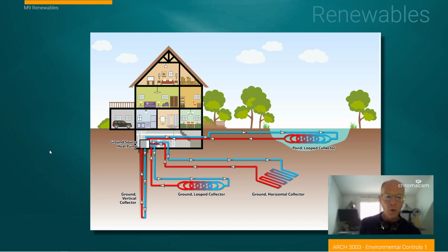So at first, I want to just step back and remind us, we've already seen this graphic before. We talk about home heating systems. In this case, the overall goal, and I'm showing a residence, but this could easily be also a commercial building. There's no distinction in geothermal heating for the type of use of the property. But we have this idea of a ground source heat pump. A heat pump is a refrigeration system that can transfer heat from one source to another, can pump it up.